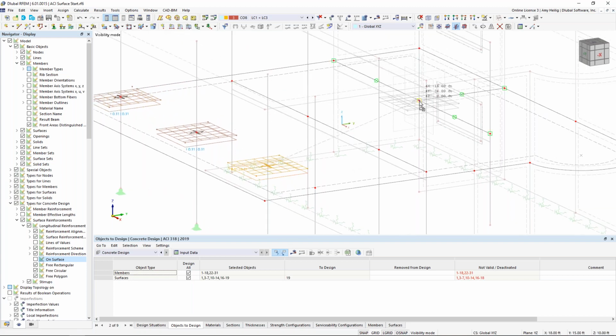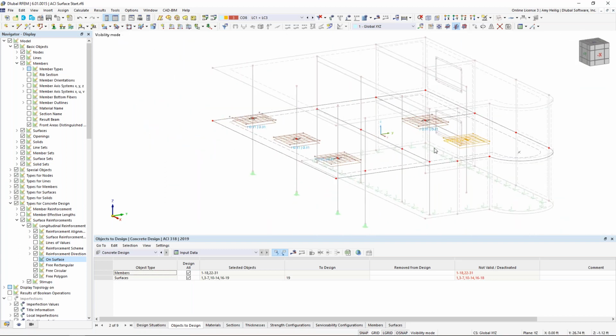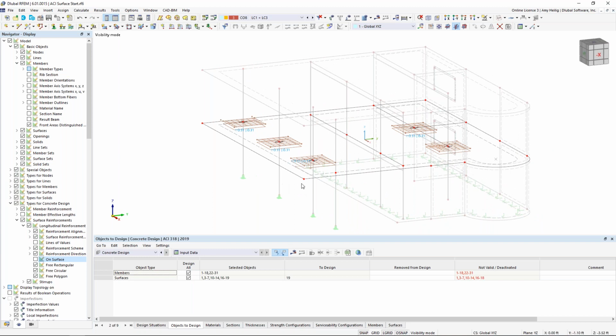I also have some areas back here where we kind of intersect with the walls and columns that need a little bit more reinforcement on the top. So of course we'd want to continue optimizing this best we can based on the internal forces. Again, we probably want to add some shear reinforcement and such to the slab. Now, taking you to another little side note here, punching shear, this will be ready actually, hopefully in several weeks for the ACI. It wasn't quite ready for this presentation, so we're not checking that right now, but that should be very close to being done within the program.